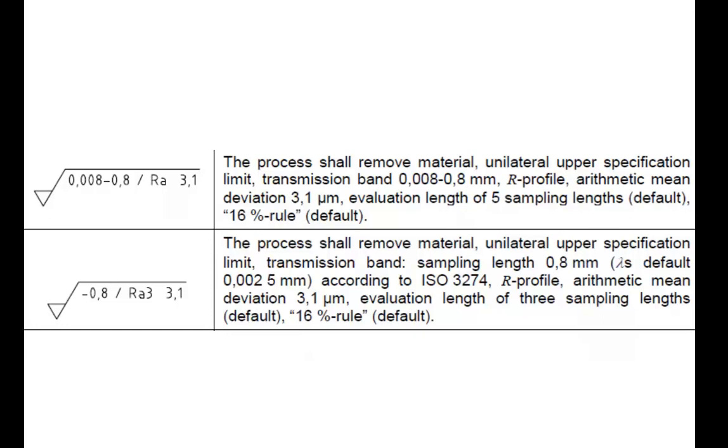But if at least one of the measured values is greater than the roughness value shown on the technical drawing, then the standard says to specify 9 additional places over the surface, and at those selected regions along the paths move the probe and measure the roughness value.